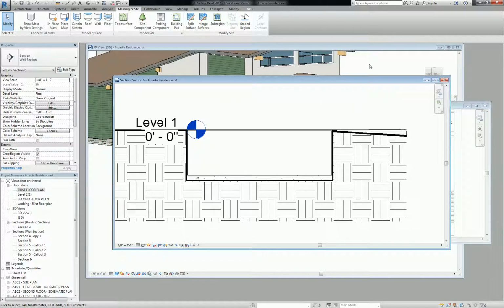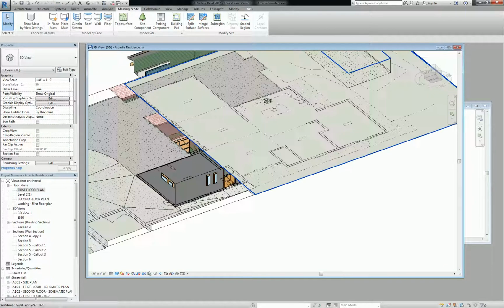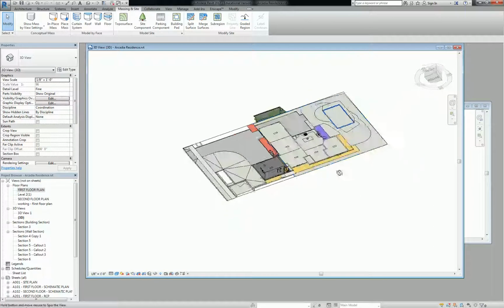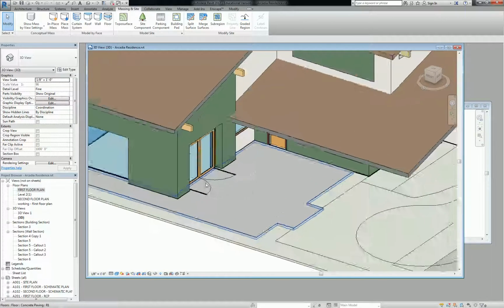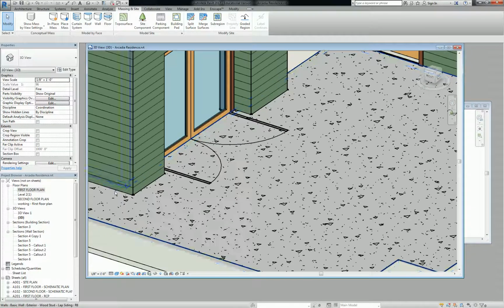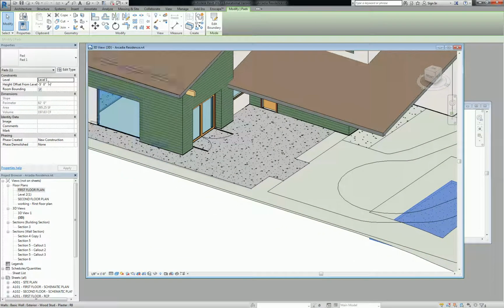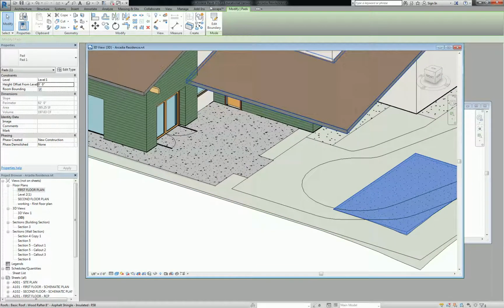So now, how are we going to apply that to our building? Well, in case you didn't notice, we don't really have a slab yet in our building. So we're going to create that slab with this family. But I want to point out that the slab will have to align and follow all of the bumps of the building. So let's modify this. We're going to set this to 0, and we're going to do an edit boundary.